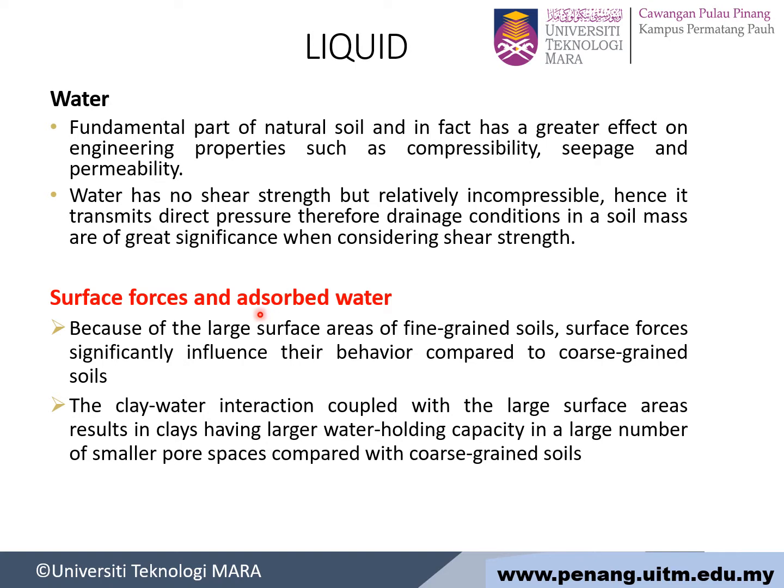Alright, surface force and adsorbed water. Because of the large surface area of fine-grained soil, surface forces significantly influence its behavior compared to coarse-grained soil. This means that fine-grained soil has a larger surface area. The clay-water interaction coupled with a large surface area results in clay having a larger water holding capacity and a large number of smaller pore spaces compared with coarse-grained soil.